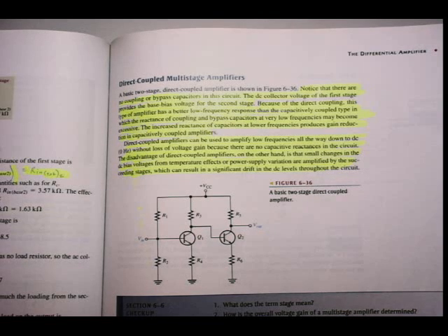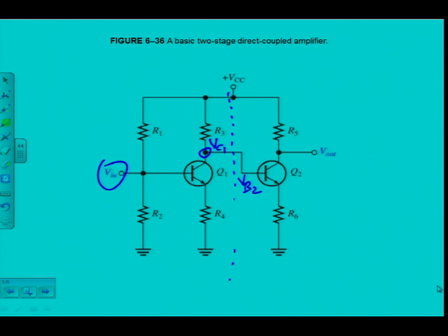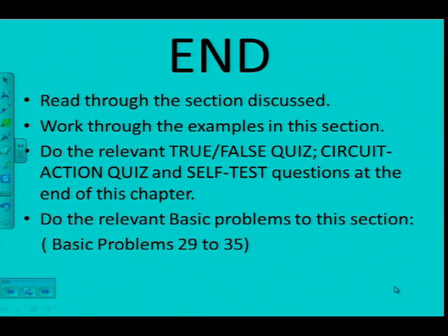Remember now, say there are outside influences that vary this voltage on the output here, then this voltage is also going to vary because of temperature and whatever. So I may get a drift in later stages as I carry on because of these voltages that may vary, because I'm using the output voltage of the one stage to drive the input of the second stage. Previously it was blocked, and then I had another voltage divider, for instance. Alright, so that's the disadvantage of this amplifier. Alright, that's the multi-stage amplifiers.